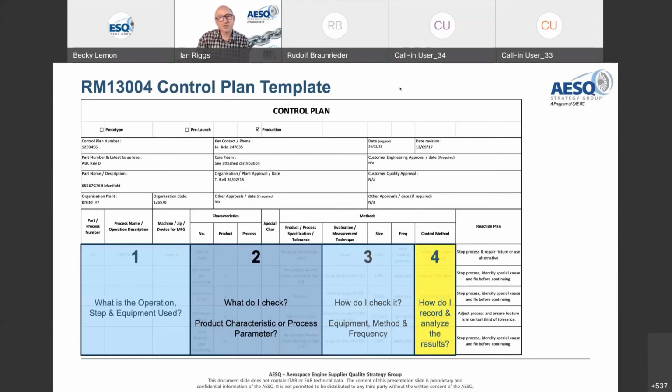How are you going to control and analyze the data? So I'm collecting all of these results, pass, fail, might be variable results. How do you want them to record it and analyze it? Like we saw yesterday, if it's variable data, it's quite easy to create trends, SPC charts, etc. If it's attribute, again, I'll be asking them to do attribute SPC.